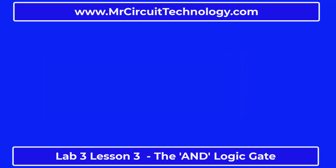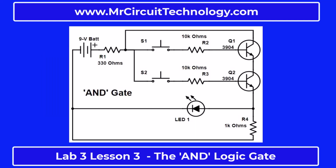Okay, let's talk about building an electronic AND logic gate. Here's the schematic for an electronic AND digital logic gate. In this Mr. Circuit Digital Logic Gate Lab, as part of your training, you will construct this circuit on a solderless breadboard. Let me explain the circuit. You will notice that this circuit is more complicated, as it has two transistors, one LED, four resistors, a 9-volt battery, and two normally open push-button switches. As in all digital logic gate circuits, when the LED is lit up, it means there's a true on the output.